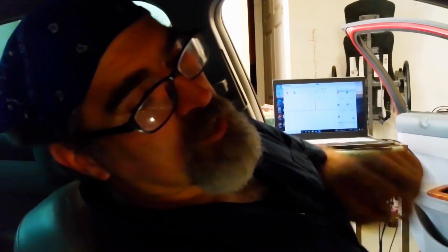We're going to get in here and see why this blower motor is not running, troubleshoot this, repair whatever we need on the output side of this, see if we have any shorts, and we're going to get that to work and see if we have any more communication issues with our module. If we do, then we're going to investigate the powers and grounds to the module. If those check out good, and we continue to set communication faults when everything is fixed on the outputs and powers and grounds, it leaves nothing but an intermittently faulty HVAC module.